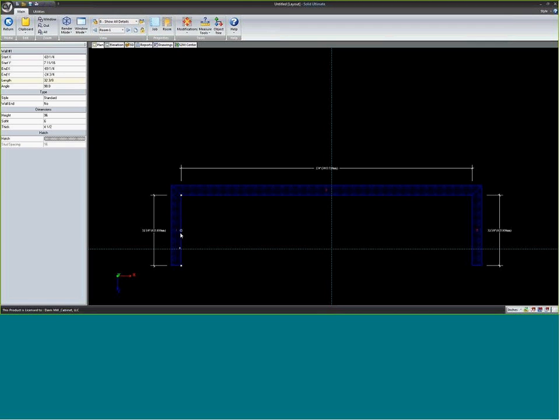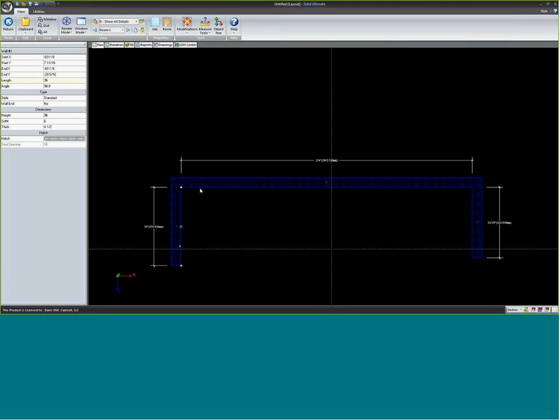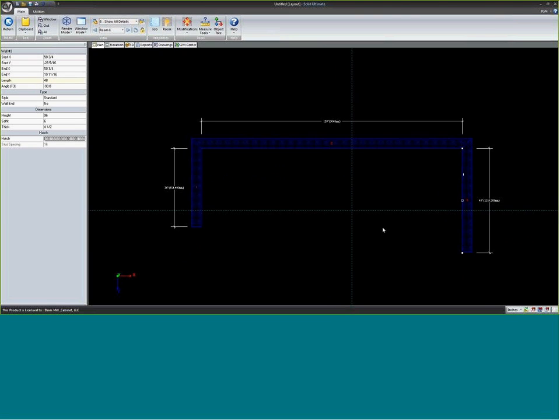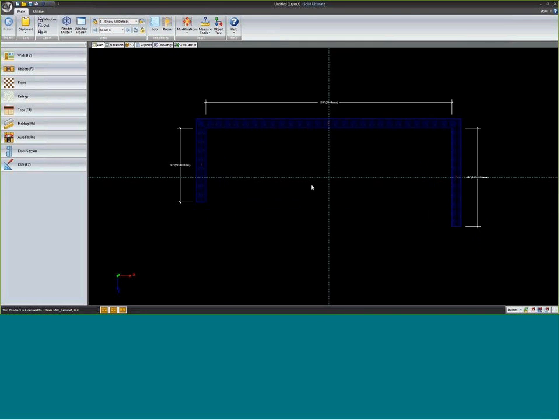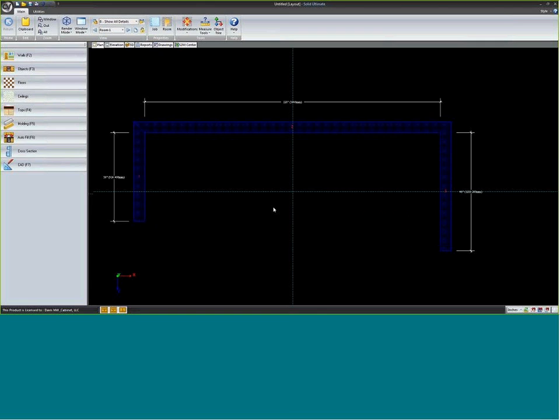Also, if you click on one wall, you can always come up here to the sidebar parameter and change its length after the fact. So I can change that to 36 inches. That wall, let's change it to 120 inches. And this wall will go 48 inches. See how that works. And then I changed how this thing's configured so I could come back up and recenter my room, and it moved those walls back around my center.